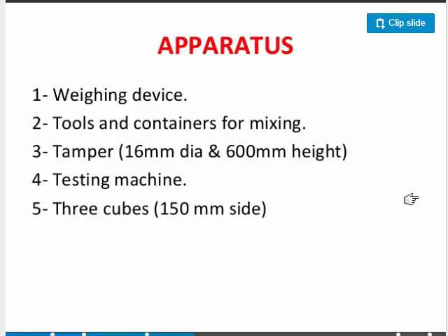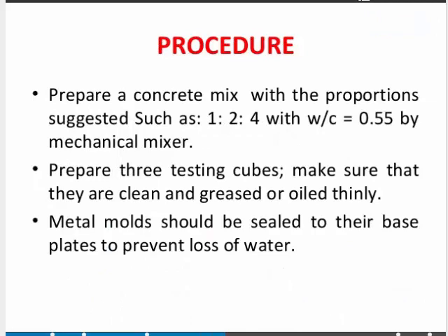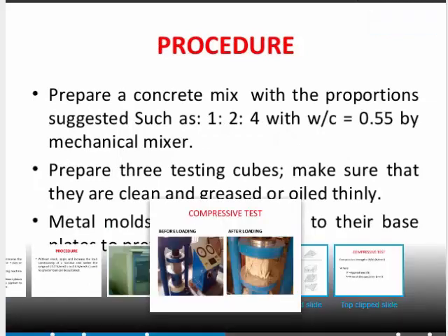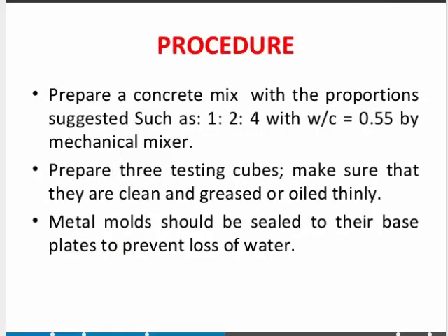These are the apparatus required for the compression testing. Prepare a concrete mix with the proportion suggested or as per the mix design. Then prepare 3 testing cubes.